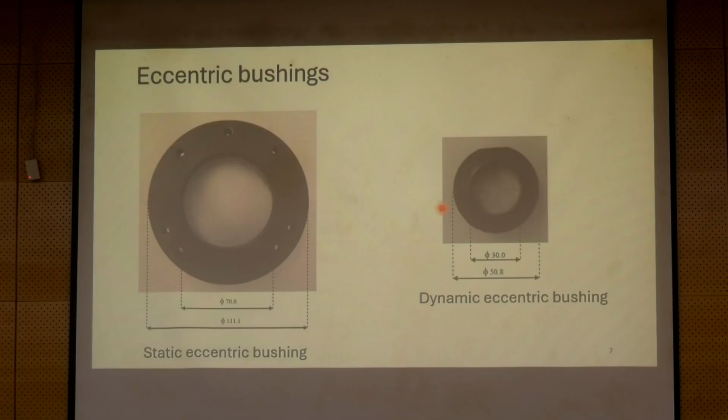So what we are trying to do is, when we put the shaft through this hole, this is not circular, it's elliptically cut. So you will see that the motion will be wobbling. So you will get dynamic eccentricity. And the margin or the distance in the way it's eccentrically cut will determine the dynamic eccentricity severity.